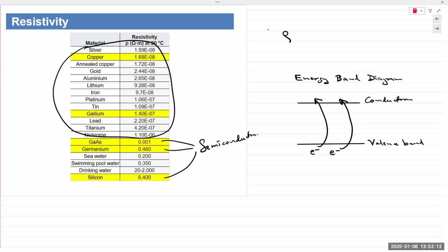That energy can be acquired in multiple ways. You can have photons coming onto your semiconductor material, it acquires enough energy, and electrons start flowing. That's how you get a solar cell. You can heat it up, meaning thermal energy. You acquire energy from heat and you're now able to break free of your bonds and be free to conduct. Or you can apply an external energy source like a voltage or a current, an external electric field, and acquire that energy. So multiple different ways. The gap between these two is known as the energy band gap.